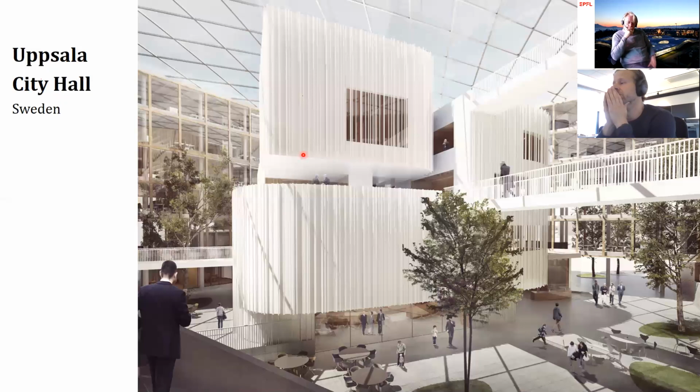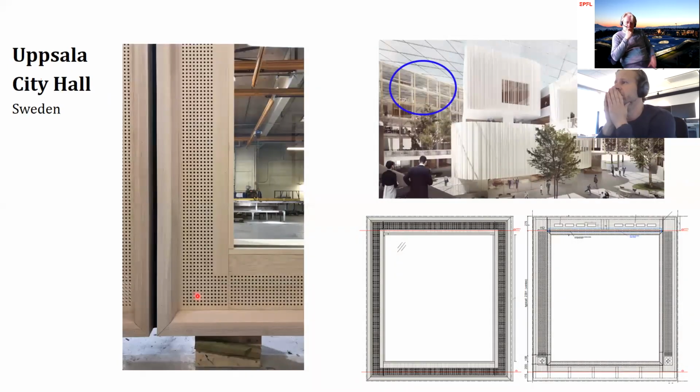We also worked with this case here, Uppsala City Hall, where we did a virtual mock-up of this large atrium space, and we used the virtual mock-up to assess what is the appropriate design goal for this space in terms of reverberation, and try out different acoustic treatments. One example of an outcome from this was that we ended up designing these sound-absorbing wooden frames, which are incorporated into the facade, a glass facade that surrounds the atrium space. And I personally think this is a very nice example of what can happen when we actually integrate the acoustics into the building design process. Then the acoustic treatment becomes a part of the architecture.